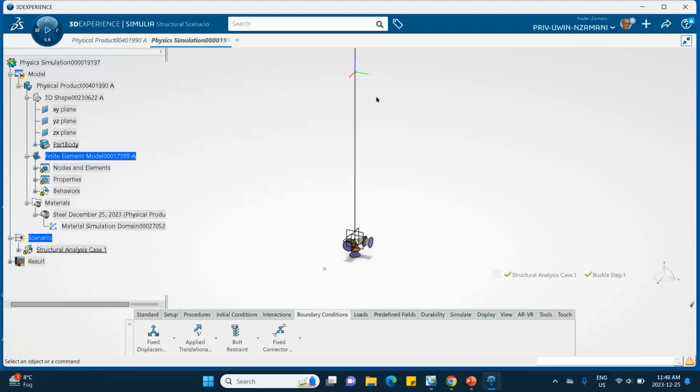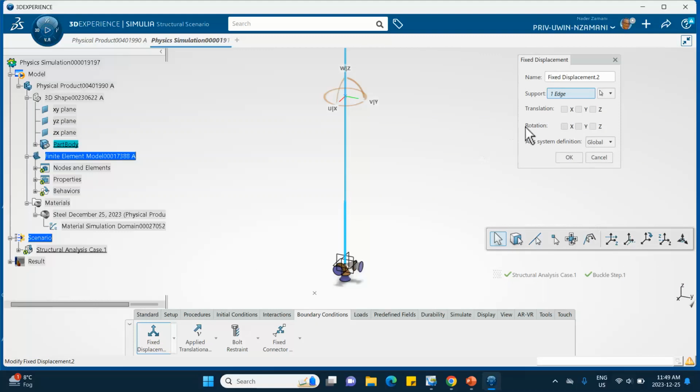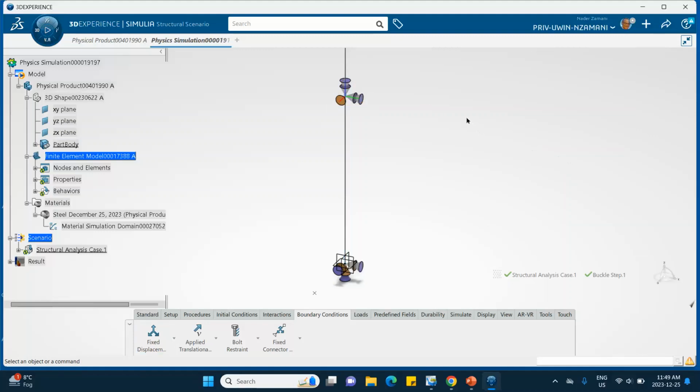And in order to make the problem two-dimensional instead of three-dimensional, only bending taking place about the x-axis, why don't I prevent this thing from moving in the x direction? So let's go to the same icon, fixed displacement, that entire line, say do not move in the direction x. It does not come out of the plane. It moves only in the YZ plane, and rotations are exactly the opposite. So this basically turns the problem into a two-dimensional problem. The two-dimensional beam problem. Okay, very good.